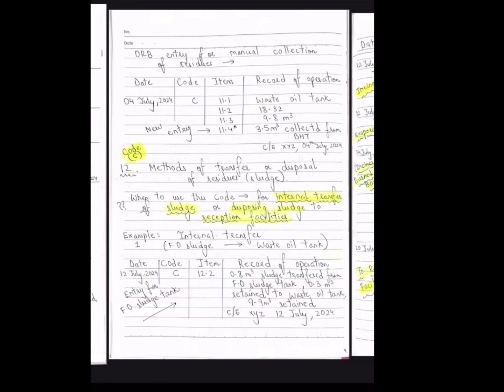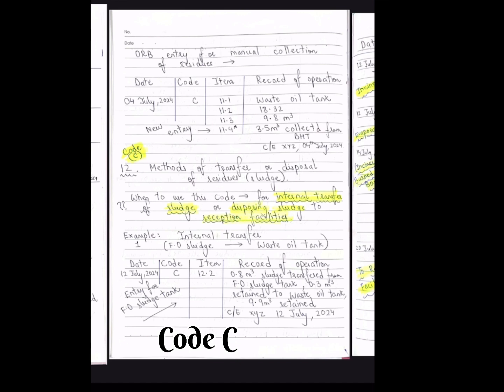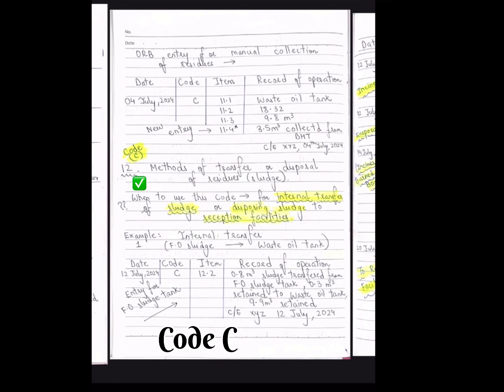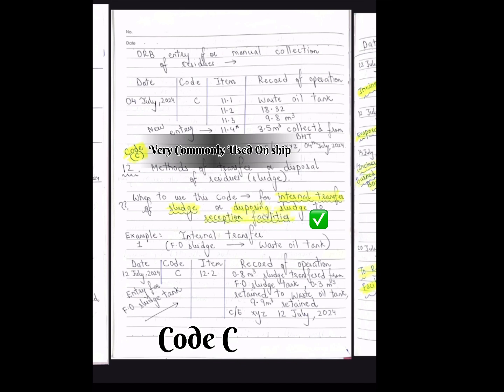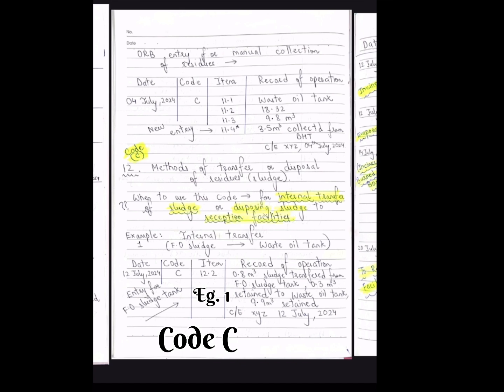So code C consists of two parts, part 11 and part 12. Now speaking about part 12, that is the method of transfer or disposal of the residue, that is the sludge. So this code is to be used for the internal transfer of sludge or disposing the sludge to the reception facilities. I have shown you some examples. This is the example for transferring the sludge from the sludge tank to the waste oil tank.